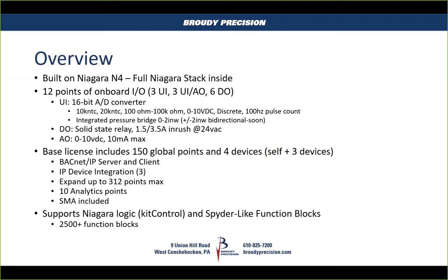The controller itself has onboard I/O, 12 points. There's 3 universal inputs, which will take resistance, specifically 20K and 10K. Discrete, it can do all the inputs can do fast pulse. I say 3 universal inputs, but it's actually 6. But 3 of them share with analog outputs.